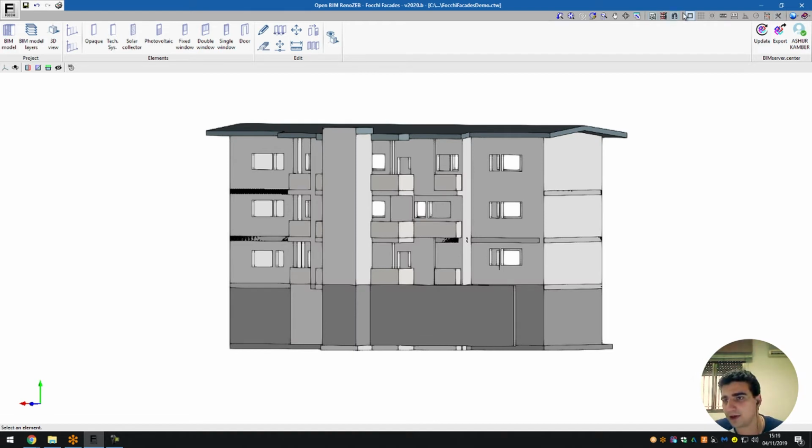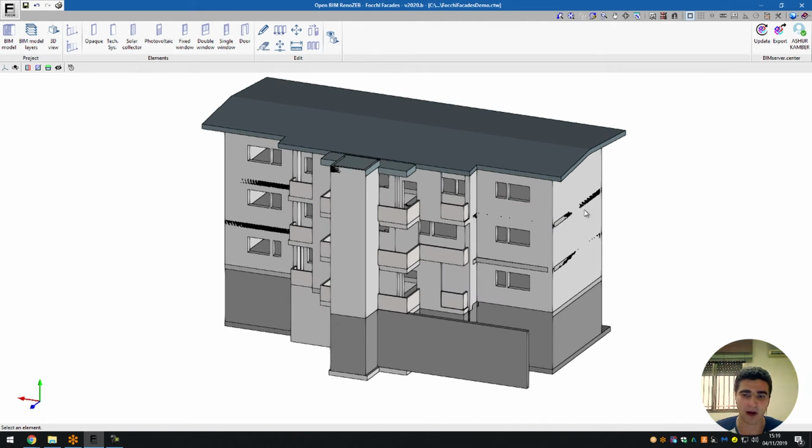These tools here, so our template tools, are not actually applicable at the moment because I haven't actually imported a template here. So I already have my model. If you had done the previous IFC Builder course, you'd know that we started with drawing templates, 2D drawing templates, which I imported with the templates manager, and then I was able to amend those templates as well.